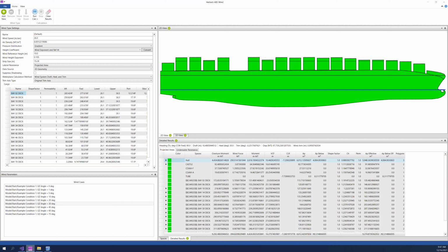Oh, all right, so we have a question: which is the preferred input file type for the new model? So I'll let you explain that one, Brandon, a bit more. Right. So in terms of the input model, it's the same ship project file, the SH2 file, and really the main changes there are going into the hull spaces and applying the appropriate wind settings there, and then just saving out the same SH2 file.